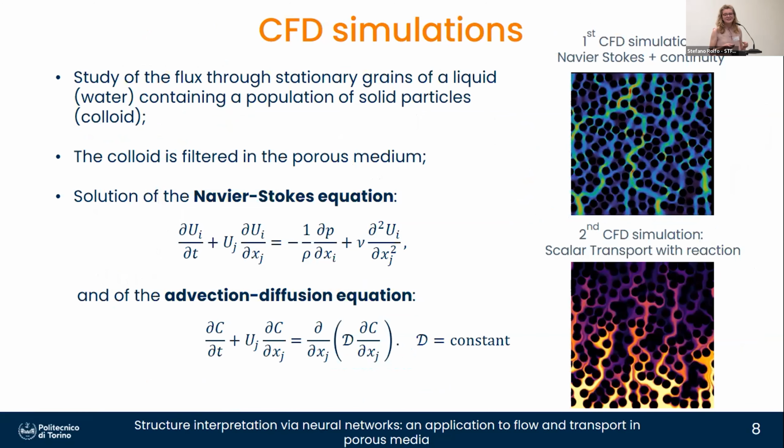So starting from the CFD simulations we solve for the production of the dataset, as I told you, we are interested in flow and transport in porous media. What we solve, starting from a geometry of a porous media, which is very simple in our application, it's just a bucket bed, is first the Navier-Stokes equation for the evaluation of the flow field, and then on this flow field we solve the advection-diffusion equation to simulate the transport of a species inside the porous medium.